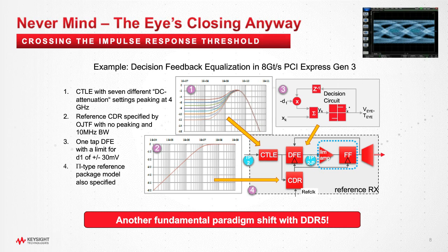For the next generation, for DDR5, that assumption is going away, so they needed to think of something new to put in there. And pretty much the only thing that hadn't been thrown into DDR4 yet was equalization. Now, there are folks who implemented it behind the scenes to improve their performance. But the first technologies to really use these kinds of approaches were the high-speed serial ones, with things like preemphasis and equalization at the receiver.